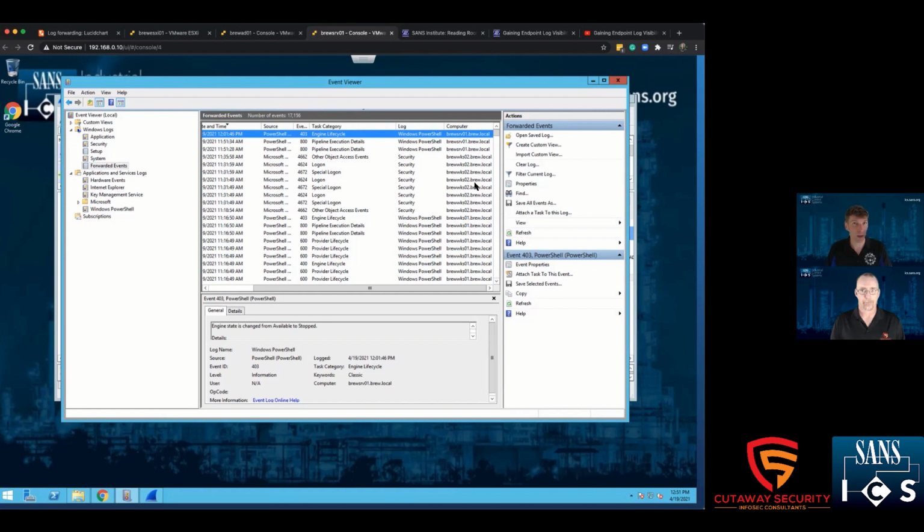Also, look at your jump boxes for remote desktop connection, your terminal services, kind of like you pointed out here. And from there, a lot of the systems in the OT environment are redundant. So pick the A or the B server of your DCS or of your SCADA system, and you can do a focused deployment on half of the environment, and then again on the other half.